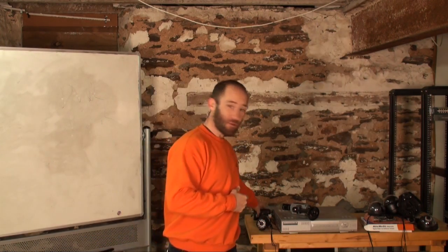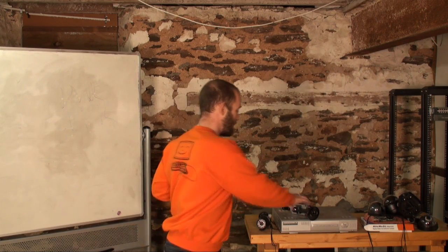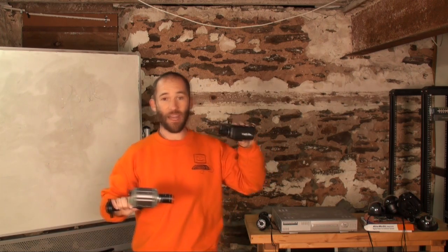You have the old analog, old technology, and then you have the new IP-based cameras. You will also hear of something called hybrid systems. So if you use surveillance equipment from a company such as GeoVision or Kodacom, they have DVRs that can accept input both from the old analog cameras and from the new network cameras. So you can have analog cameras going back to BNC connectors on the computer, and it will also bring in information from these IP cameras.